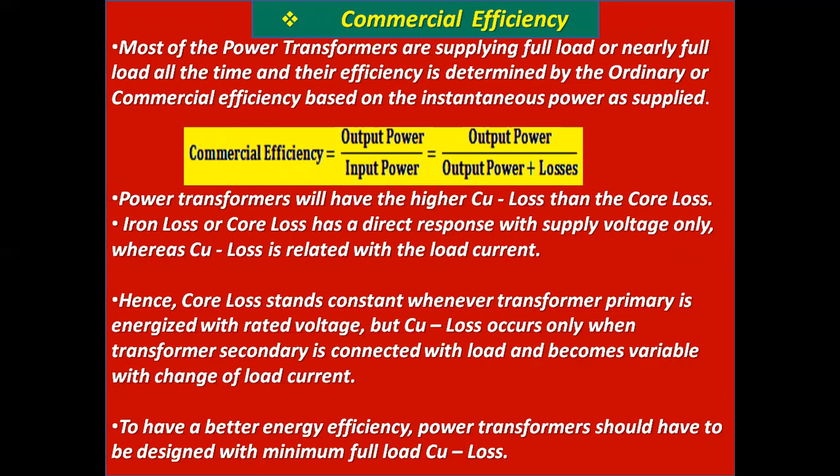Iron loss or core loss has a direct response with supply voltage only, whereas copper loss is related with the load current.